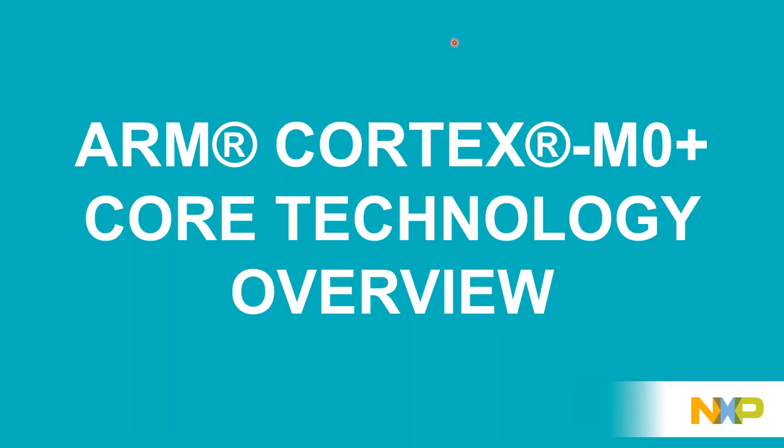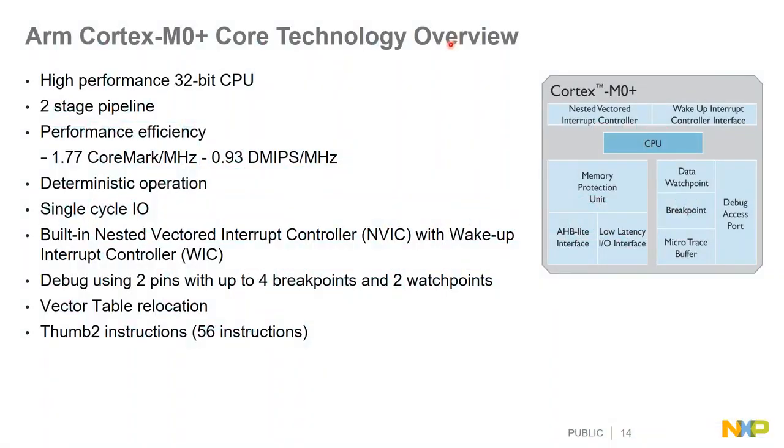I would like to introduce the ARM Cortex-M0 Plus. This is a high-performance 32-bit CPU, which has got a two-stage pipeline. That is quite good, that the performance efficiency is very good. It's good that it's a single-cycle input-output. It has got wake-up pins, also 2 pins for SWD for debugging with 4 breakpoints and 2 watchpoints. And there is a vector table relocation if you need it, and it's running Thumb-2 instructions.